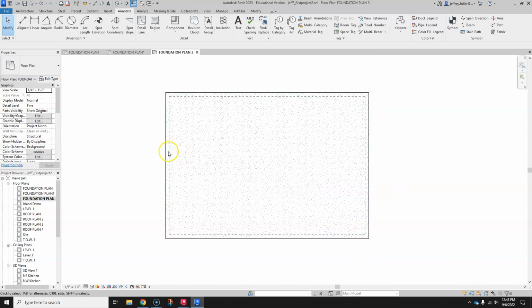All right, and one other thing that you see a dashed line over here, and I forgot to show you one thing, is when you actually, to create that dashed line, you need to go and put on a thickened edge type footing for your design. Now, we can do it or we can't do it as far as in Revit. We always have to draw it at least and represent it that way. But I go ahead and just do it as 3D.